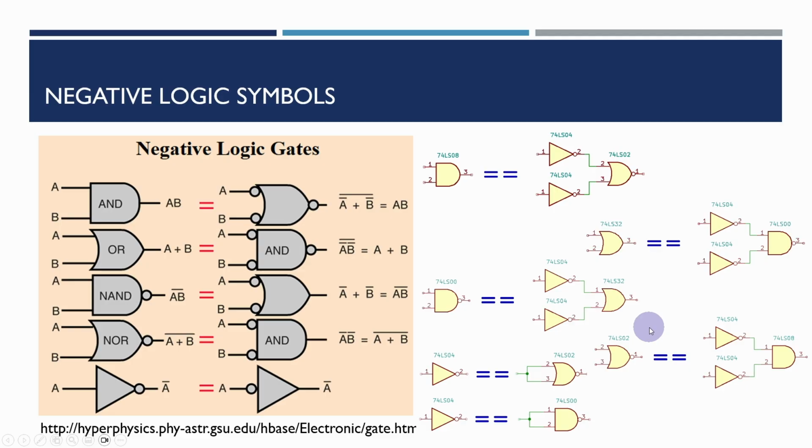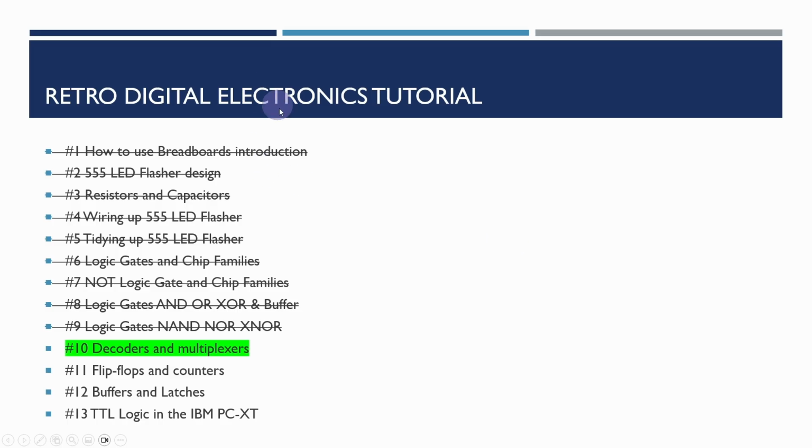And certainly if you're simplifying rules and things like that, if you have more complex combinations of things, you may very well find that there is a simpler combination that actually achieves the same inputs and outputs. And one of the things that WinCUPL will do, with some of the optimization modes on it, is simplify the rules that you defined and give you the minimum set that you require to actually implement your logic. So that's all I was going to do for this video.